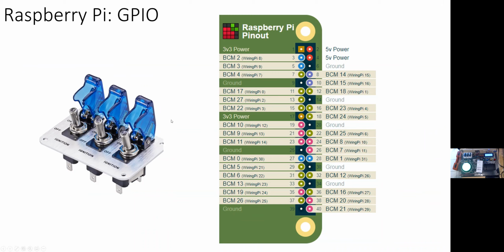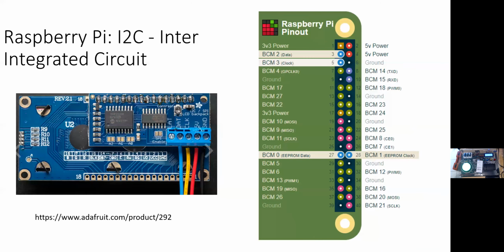For things like the toggle switches and the push button switches, basically they could connect up wherever you wanted to, and these are all the options. These are the standard pins. The biggest challenge was working out logical groups of them. For example, this has 3, I need 3 switches for this, but then I also need 3 pins to control the light. So that's 6 pins. So where is there somewhere with 6 pins relatively close together so that your wiring doesn't go all kind of crazy? So that was the standard ones.